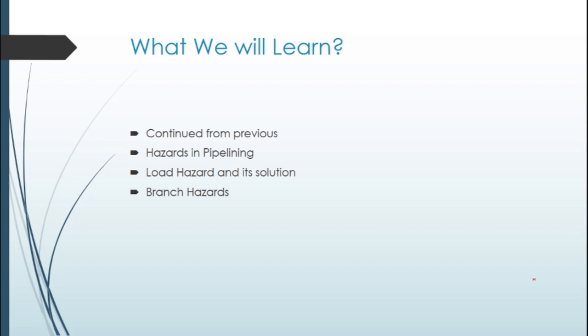Similarly, we have branch hazard. Branch hazards are due to the branch target, which cannot be determined before the third clock cycle, and the branch condition, which also cannot be determined before the third clock cycle. So in the normal process, by the third clock cycle, two more normal sequential instructions are already fetched and have started execution, which should not be there in the pipeline. For those cases, those two next instructions have to be flushed from the pipeline to make it work properly.